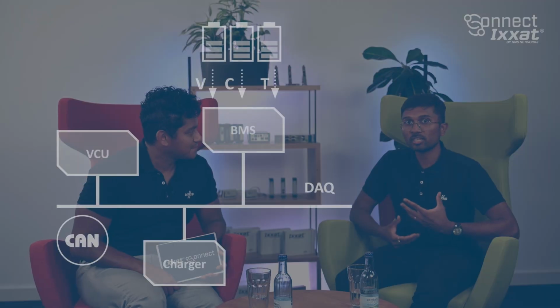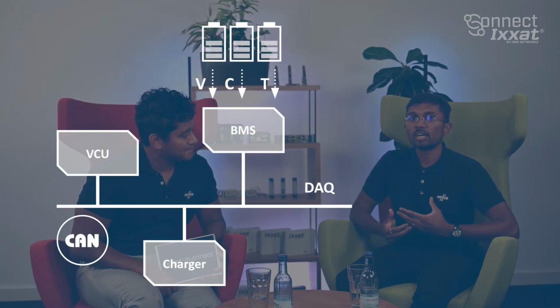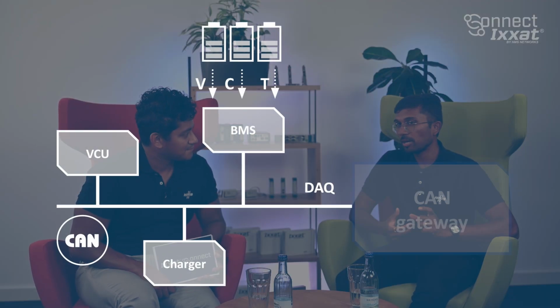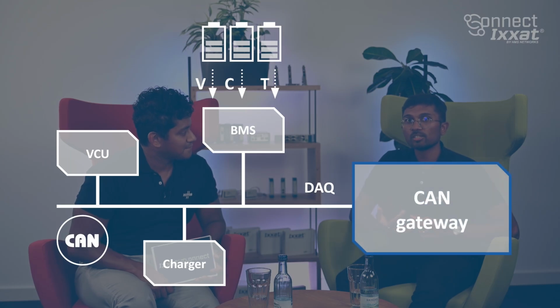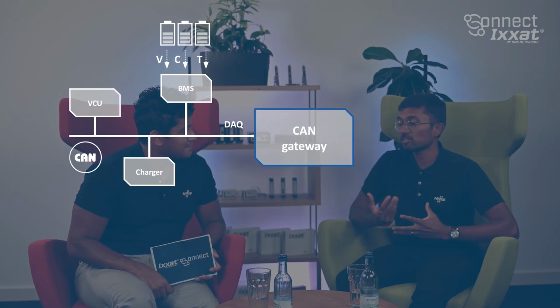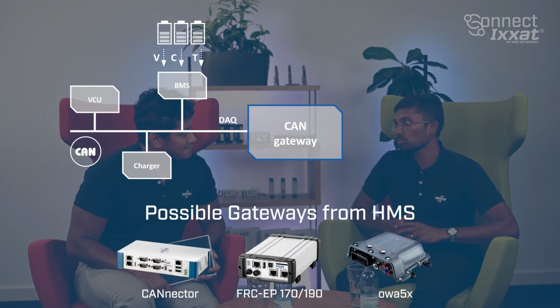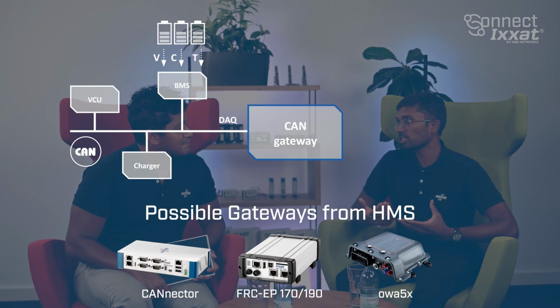This data is being transmitted to the CAN gateway. The gateway has different kinds of filter settings to sift through the traffic on the CAN bus and select the relevant battery data for further processing. Mechanisms like error handling and managing issues like CRC errors on the CAN bus, all this is being taken care of from the gateway side so that there's a smooth data transmission.